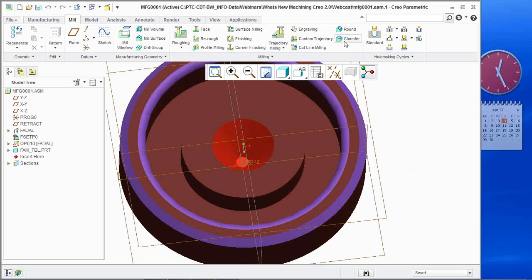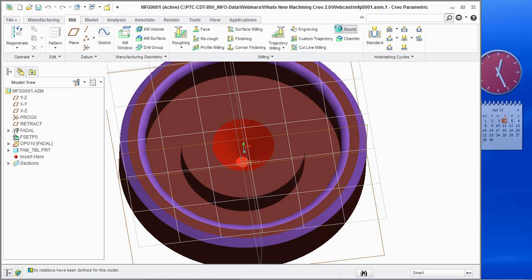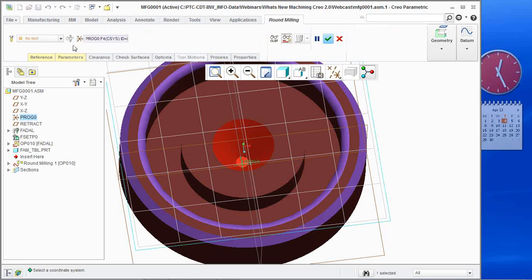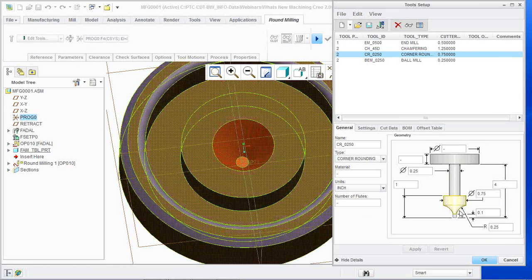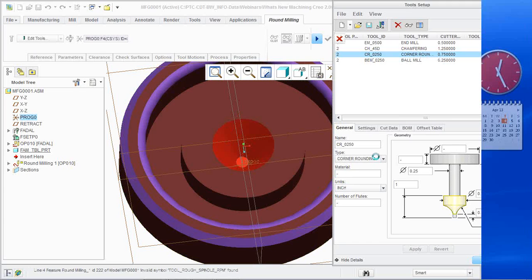Okay, so here is my round toolpath. I pick it, and again, go through the same type of interface we just talked about. I created the tool. If I pick it, just so you can see what this tool is, essentially here's the shape. All I did was give it a name and configure some sizes, some pretty generic stuff. Obviously, you can play with most of these values for whatever reasons you need to. I just gave it a name so that it's identifiable. There it is. We'll say OK.